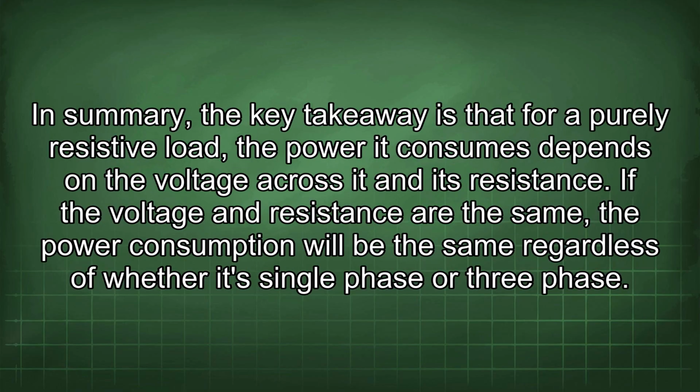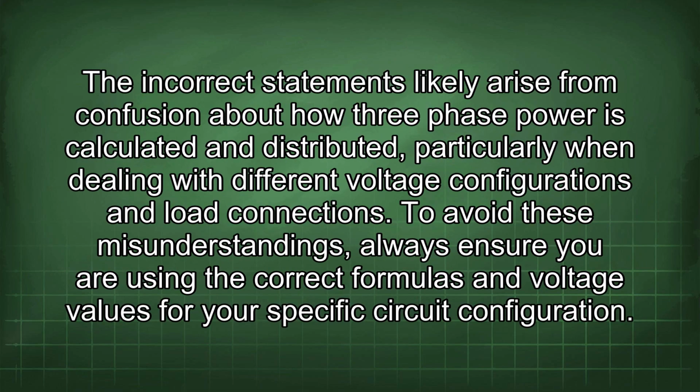In summary, the key takeaway is that for a purely resistive load, the power it consumes depends on the voltage across it and its resistance. If the voltage and resistance are the same, the power consumption will be the same regardless of whether it's single-phase or three-phase. The incorrect statements likely arise from confusion about how three-phase power is calculated and distributed,